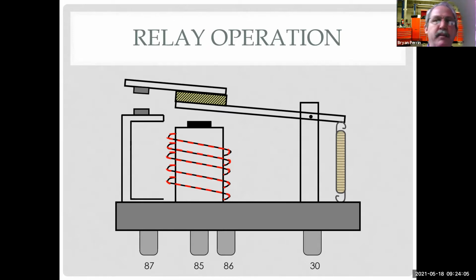So anytime my high beam headlights are on, there is power at pin 86. Pin 85 is the ground for that load, so pin 85 goes back to a switch on the dash that turns the ground on and off. Just because I have my high beams on doesn't mean I want driving lights. So I need two ways of controlling this.